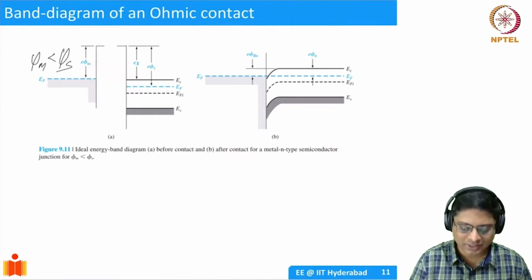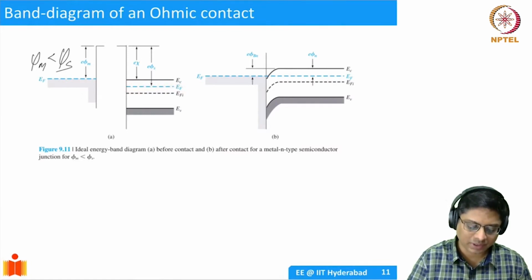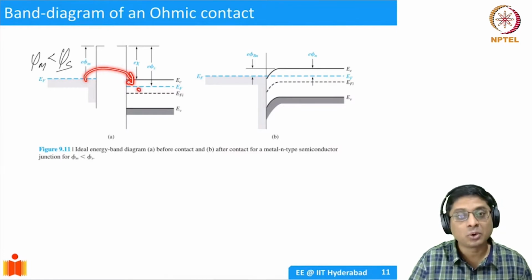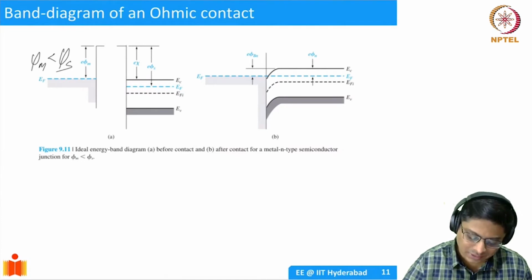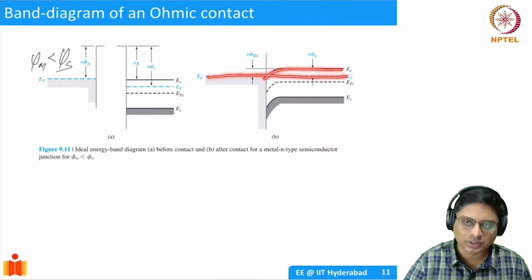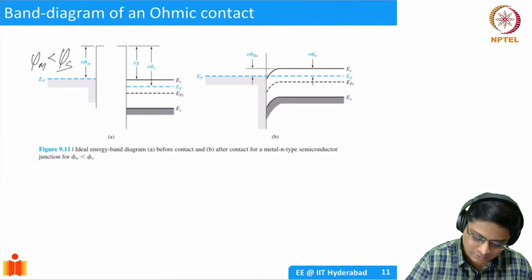The other way it won't happen, because the electrons in the semiconductor have smaller Fermi energy. They can't transfer into the other side, but the opposite transfer happens. So when this happens, it's an N-type semiconductor and we are adding more electrons, right? We're increasing the concentration of electrons in the semiconductor. That's why you will see that in this case, the EF is constant, but the bands are bending downwards. So this point here